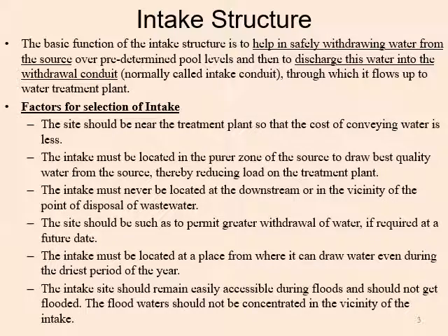So there are some factors to select an intake structure, like where the structure will be constructed. The site should be near to the treatment plant so that when we are conveying the water, the length of the conduit or pipe should be less so that the cost will be less.